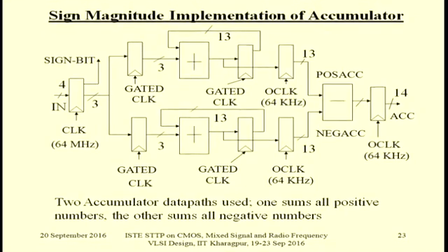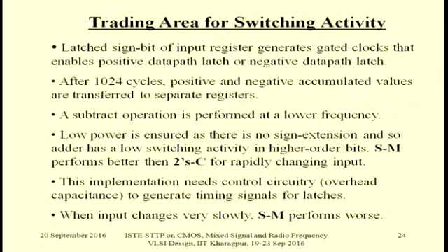Okay, so the overhead capacitance is quite sizable, but as far as the result is concerned, that is more important. When all the negative numbers are coming here or all the positive numbers are coming here, the adder sum output transition activity will not be much.